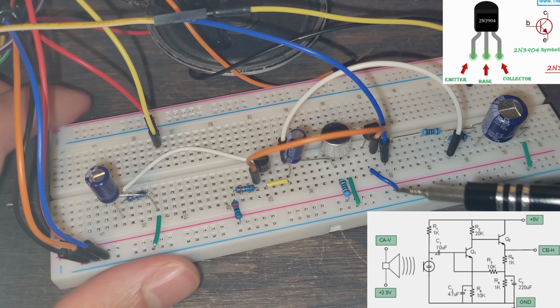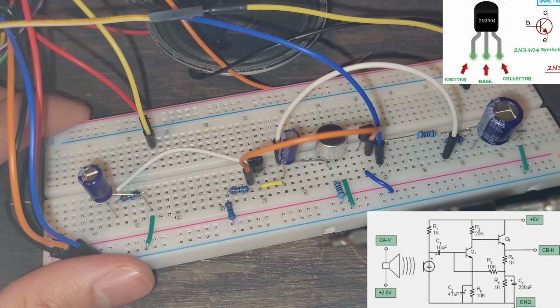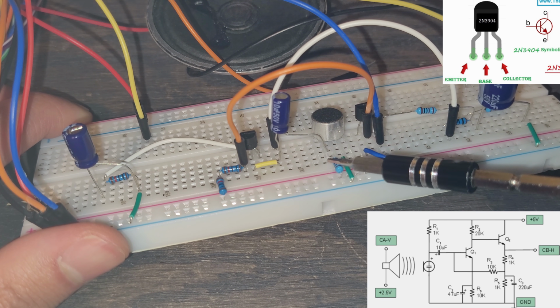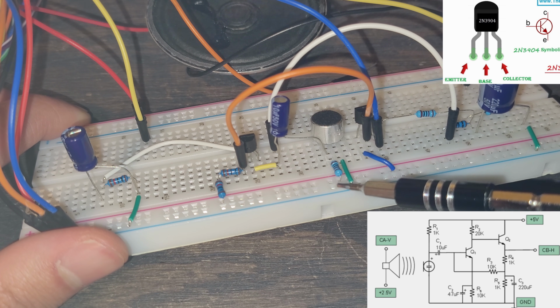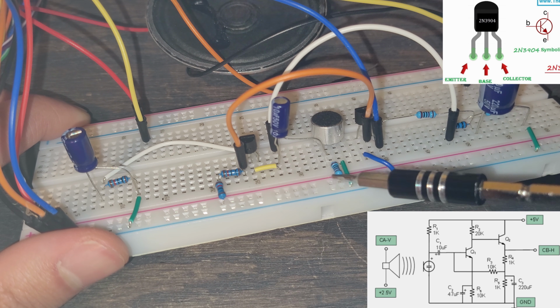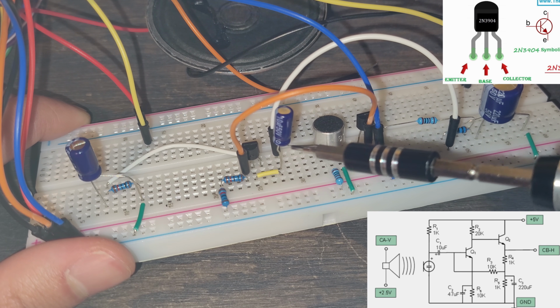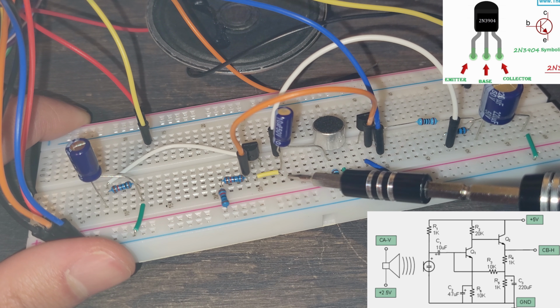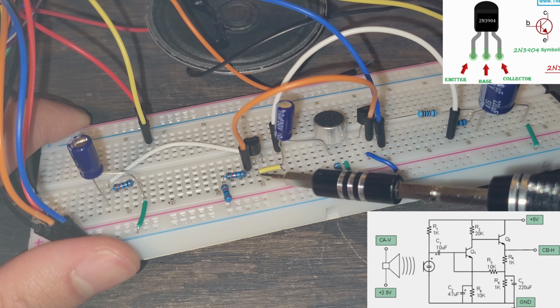Now let's look at the row underneath. We've established everything. So let's, again, left to right. We have our 10 microfarad capacitor, right? And we can see that it goes from the 1 kilo ohm resistor. It's in parallel with it. It's going to go out this way, and it's going to end right here. Now it's going to connect to the base of our Q1, which it does right here.